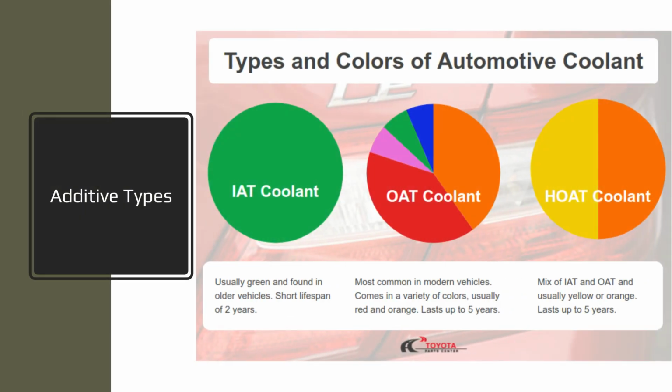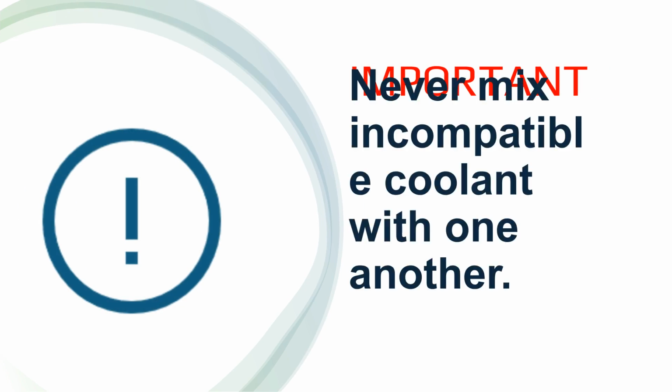Choosing the right coolant is critical, as different formulations are designed for specific materials and engine types. Always check your manufacturer's recommendation. A crucial safety warning: never mix incompatible coolant types. Doing so can cause clumping and damage your entire cooling system.